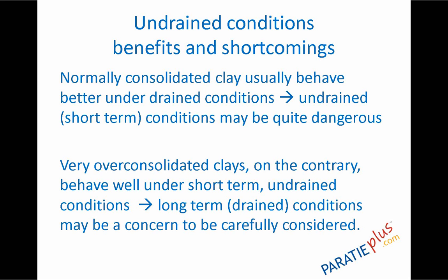Just taking a look at clay, we can say that generally speaking, normally consolidated clays with very small shear strength capacity behave better under drained conditions. So undrained conditions that occur just after the application of loading may be quite dangerous.